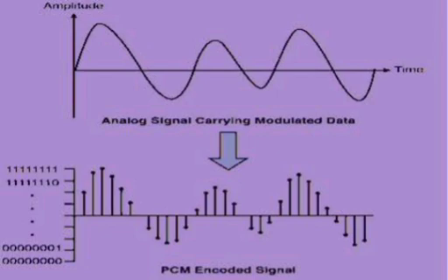Entropy: the average information content per symbol in a group of symbols is known as entropy and represented by H. If you have m symbols with probabilities of occurrence p1, p2, and so on, pi, pm, then entropy H will be H equals sigma i equals 1 to m of pi log base 2 of 1 by pi bits per symbol. Entropy will be maximum